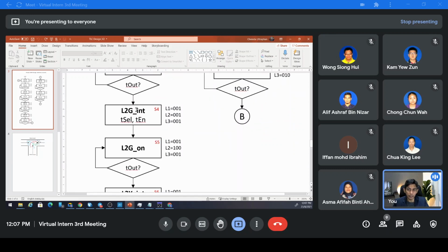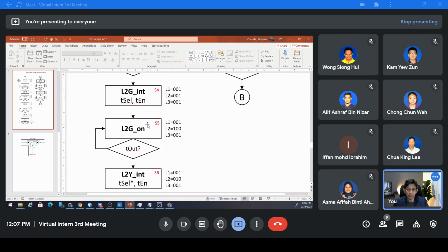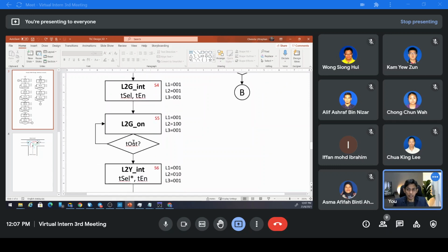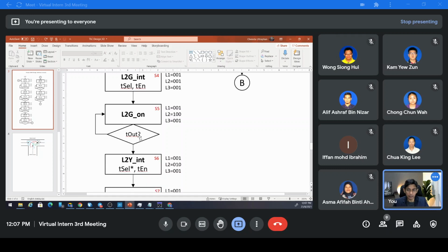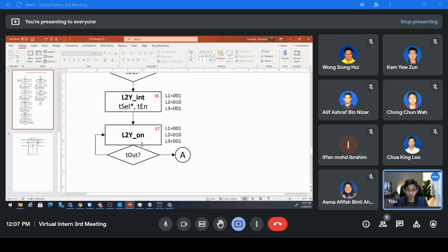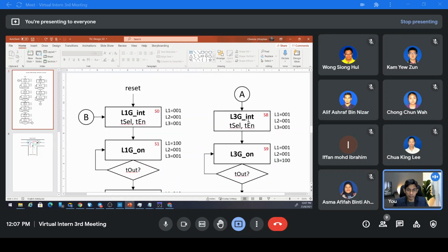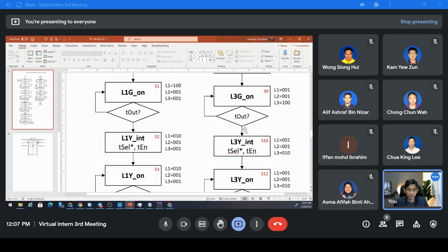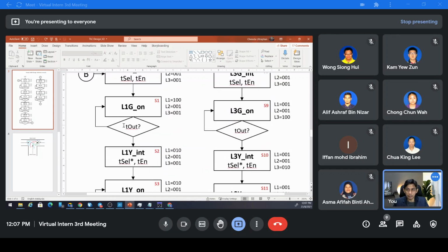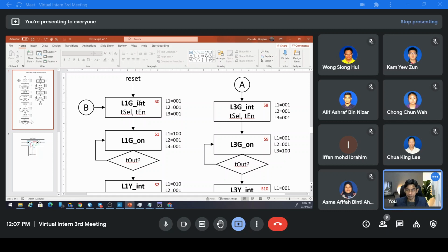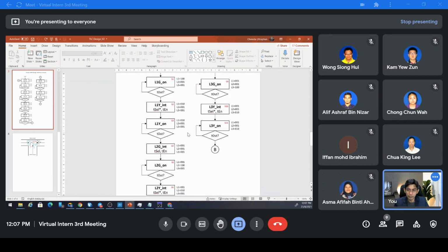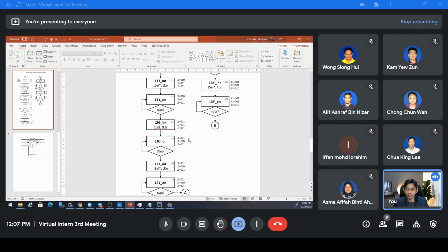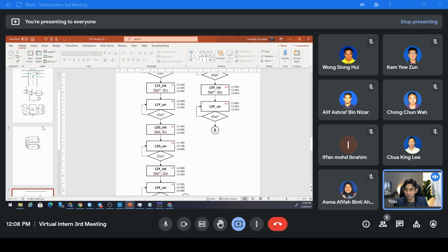We load the timing, 20 seconds, into the counter here at the initialization, and then stay here for 20 seconds, green, and then yellow, and then now green for L3 and yellow for L3, and go back to green for L1, right? So this is the ASM chart for a simple sequence like this.